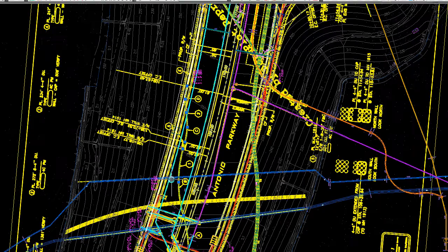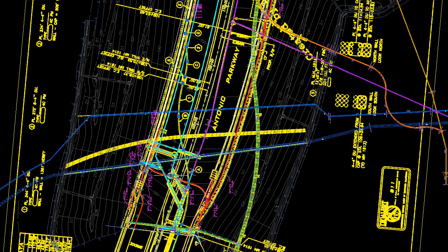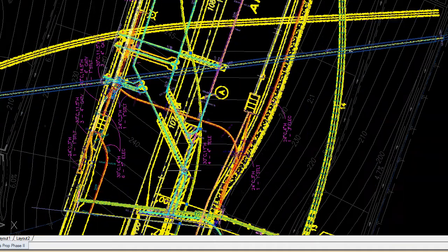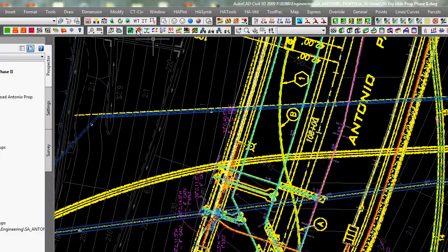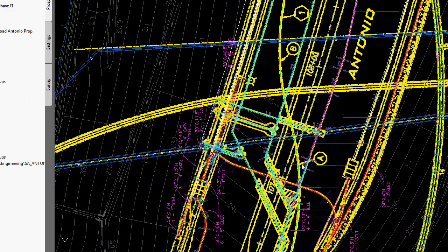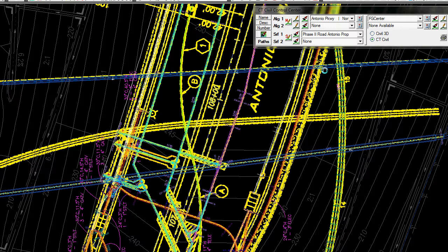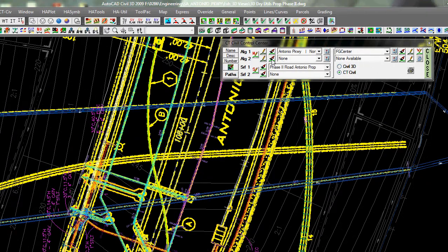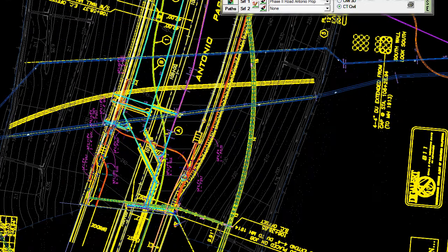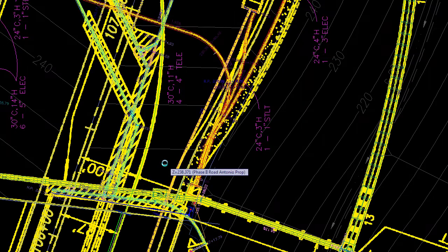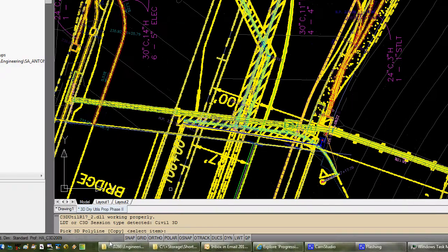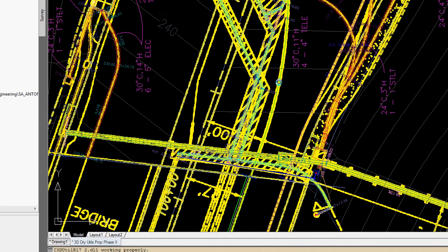So the tools that we have want exactly that as a starting point. So I'm going to go to our 3D alignment tool, and it's starting up its alignments database. This is for what I call published alignments, but what we're doing right now is the data is only going to be contained by this polyline, as you'll see. So it's asking me to pick a polyline, right? If I pick one that's not a 3D poly with the smart data on it, it knows I want to make a new one. So it says, okay, making new alignment. Now it says pick point. So it wants elevation points.